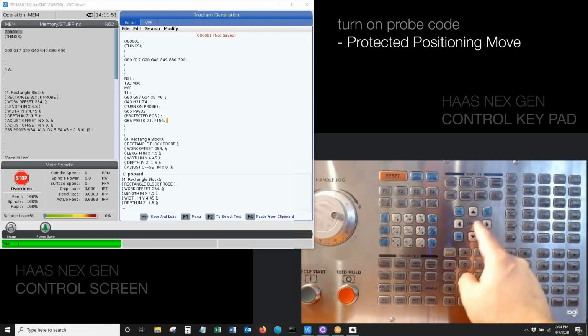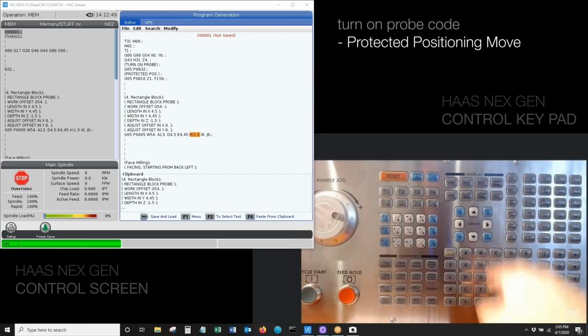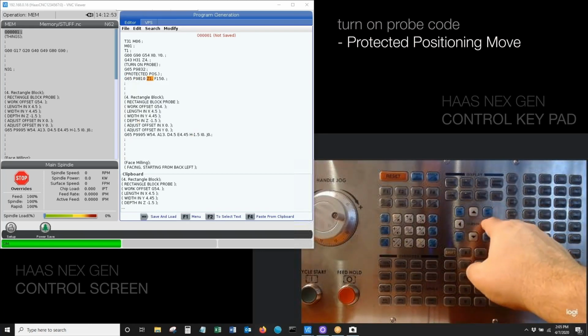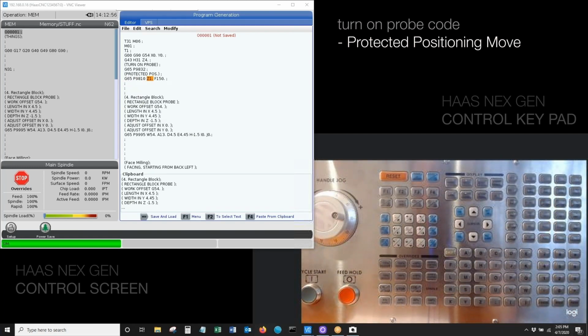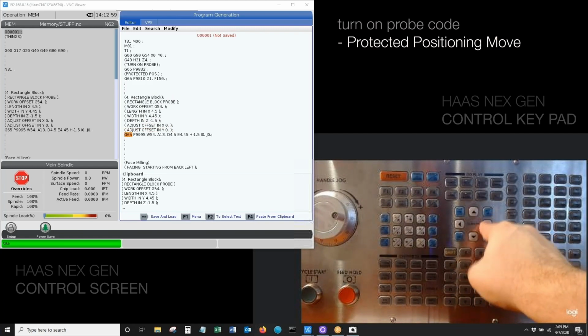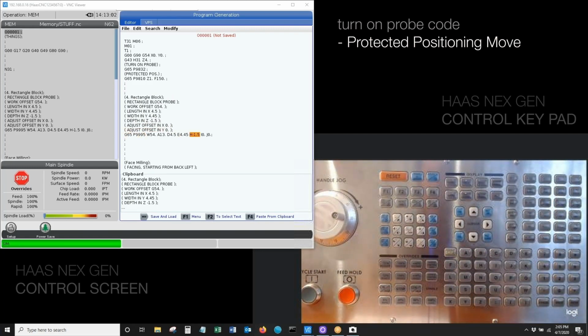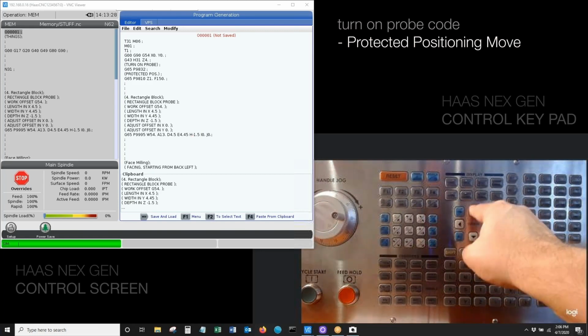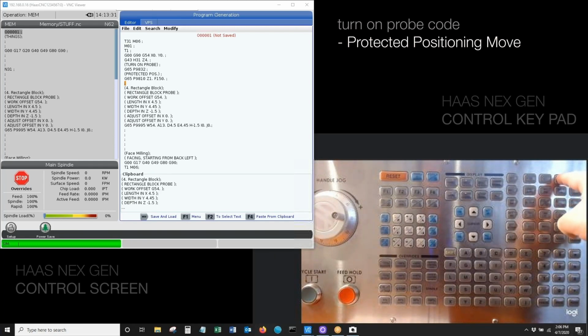Now we have that position 1 inch above the part. So if I actually parked my probe at 1 inch above my workpiece, and I asked in the routine, which is this H value, which we filled out in the template, the DPS template, to go from its current position down 1.5 inches, then what that basically means is that the ball of the probe tip will be 1/2 inch below the surface of our workpiece, and that's where we're going to probe to find our X and our Y center of our part. So all I have to do now is just get rid of that spacing there.